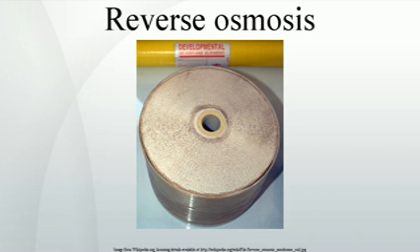Examples are the DWER, the rotary pressure exchanger, and the Danfoss energy recovery pump, a reciprocating piston pump having the pressurized concentrate flow applied to one side of each piston to help drive the membrane feed flow from the opposite side. These are the simplest energy recovery devices to apply, combining the HP pump and energy recovery in a single self-regulating unit. These are widely used on smaller low-energy systems. They are capable of 3 kWh per meter cubed or less energy consumption. Examples are the Clark pump, the Katahdin desalinators, and the Spectra Pearson pump.